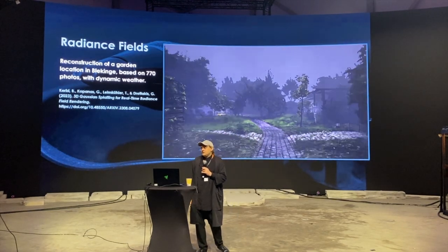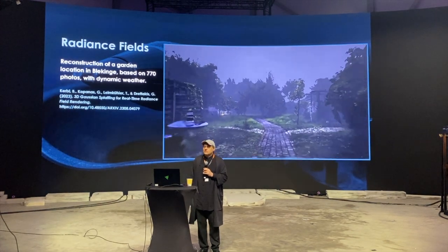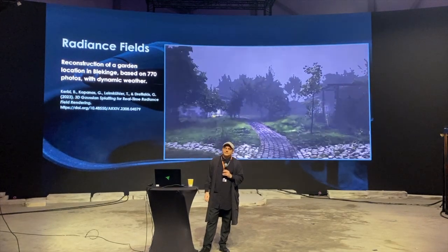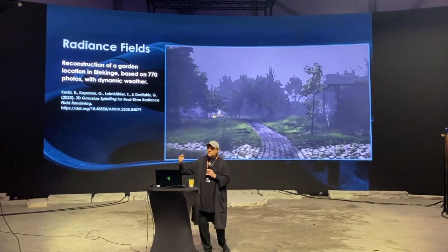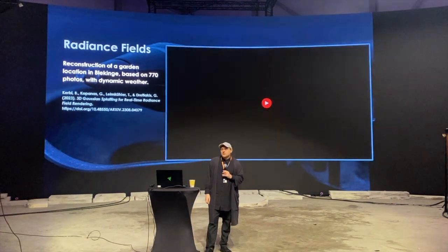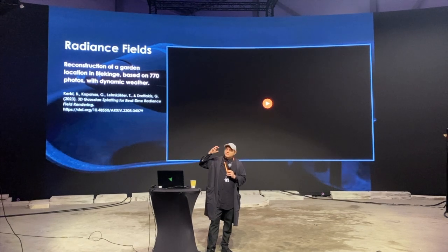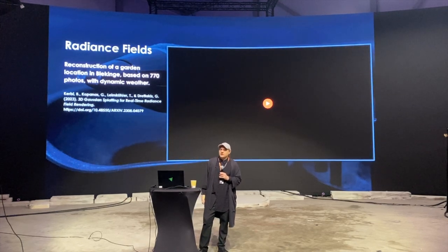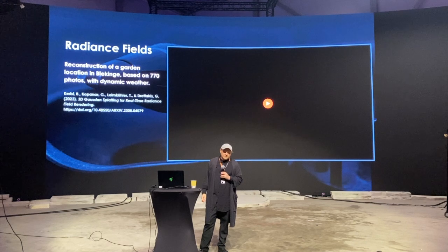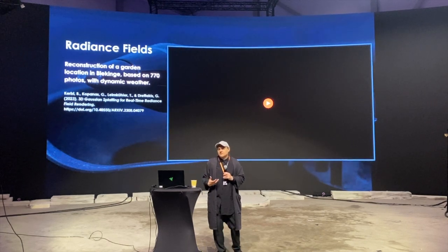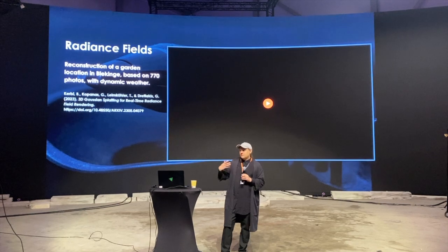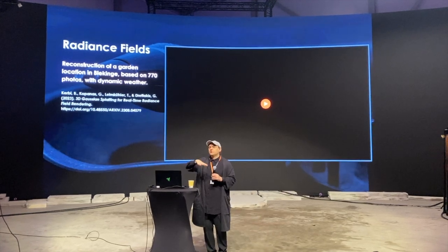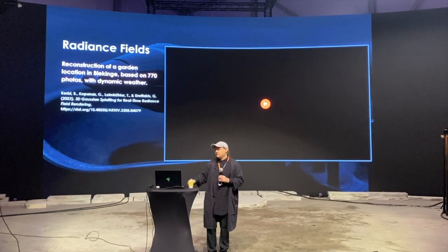And 3D Gaussian splatting is an optimization of that using a conditional point cloud with particles that have position, color, rotation, size, and the point cloud is also dynamic, so it is responding to the position of the camera and can change properties depending on the camera view. And that means that the difference between that and photogrammetry is that you can replicate areas that reflect light, like glass or transparent areas, or sometimes even puddles or seawater that is still.